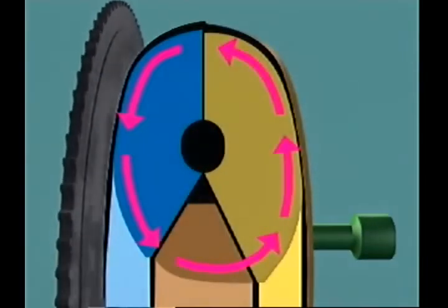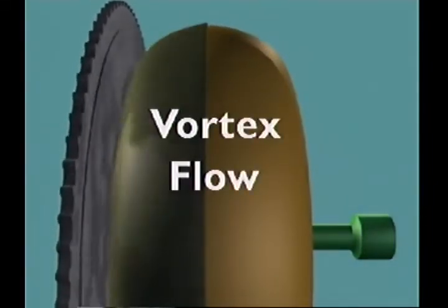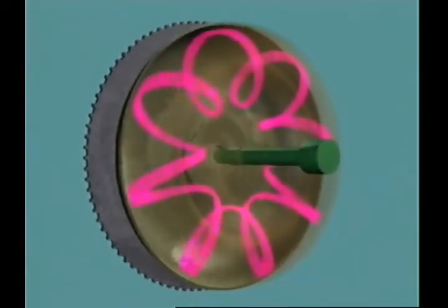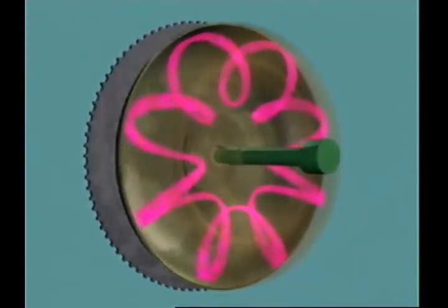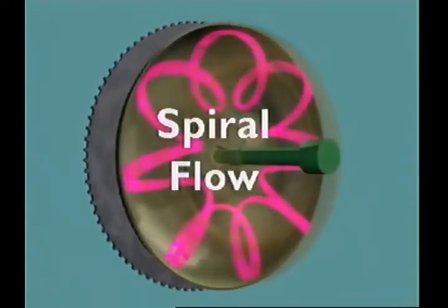During torque multiplication, the shape of the converter case makes the fluid flow in a circular motion through the impeller, turbine and stator. This is known as the vortex flow. Combining these two fluid flows produces a progressive circular or spiraling motion. This is known as the spiral flow.